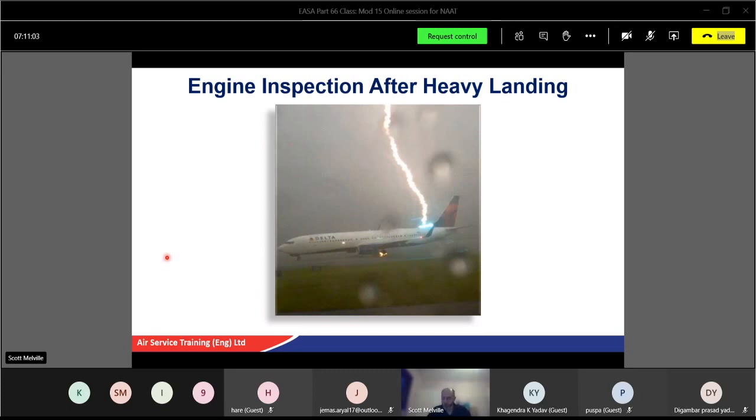Maintenance, just have a run through. What's the purpose of flat rating? It is given by the manufacturer, the maximum thrust amount to be achieved in a certain temperature. That's it. Flat rating allows the engine to produce a constant rate of thrust over a wide range of ambient temperatures without working the engine harder than necessary. In other words, a guaranteed amount of thrust depending on where you are within that envelope.